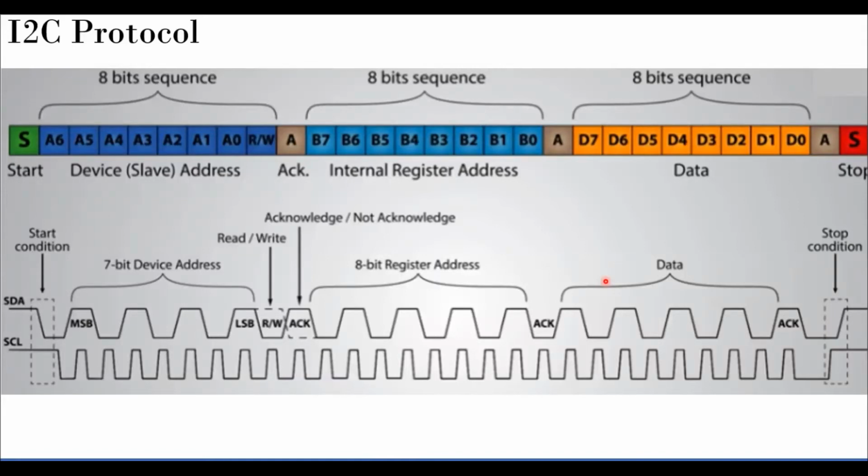So basically, we need to have a start bit, the address bit, the device address I'm saying, then the read/write option. You send it over. Wait for the acknowledgement. Acknowledgement done. You send the internal register address if it exists. If it is not there, it's not needed. Again, you wait for the acknowledgement. You send the data, or you wait for the data to arrive. Again, you wait for the acknowledgement. Okay? Then you issue the stop bit. Communication stop. So it's slightly complicated compared to SPI or compared to UART, but it's a very, very popular tool because of that extreme possibility.